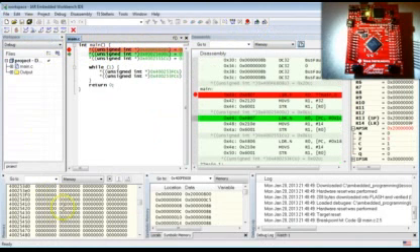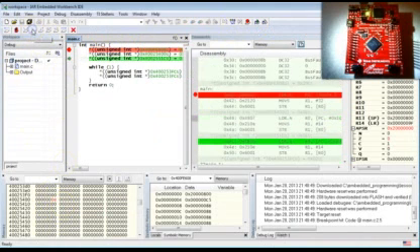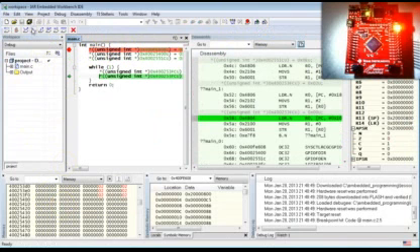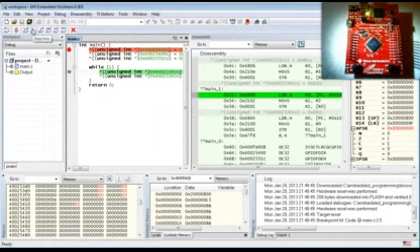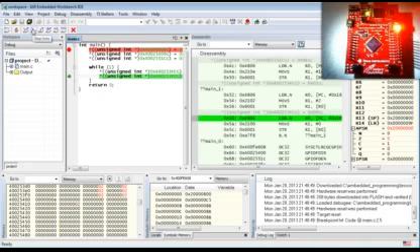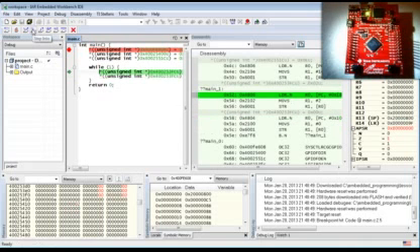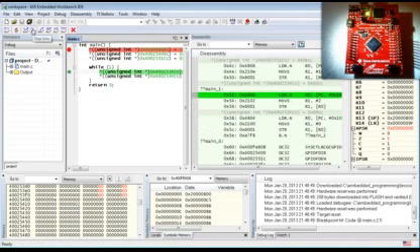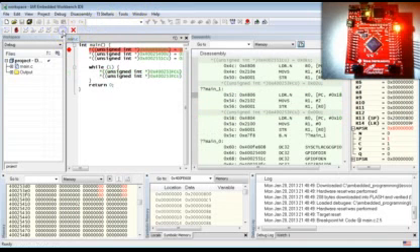Note that setting the clock gating register wakes up the GPIO-F block as expected. Here you can see that the red LED lights up, and now it goes dark again. The endless loop also seems to be working. Well, if everything looks so good, let's run the code at full speed by pressing the Go button. What the heck? The LED stays on all the time.